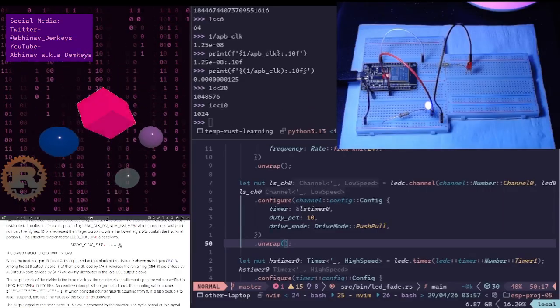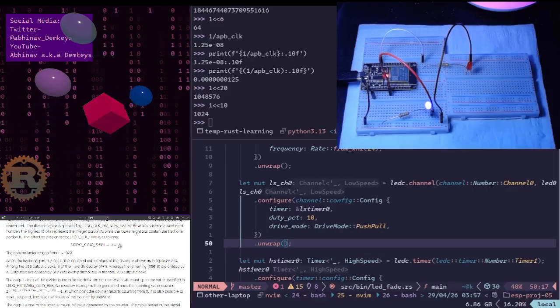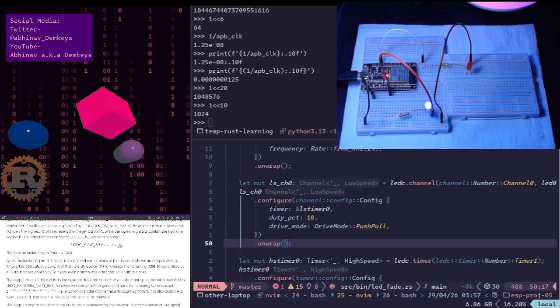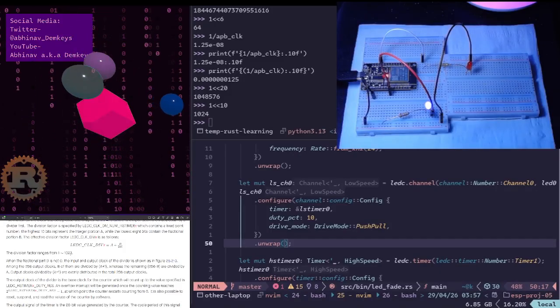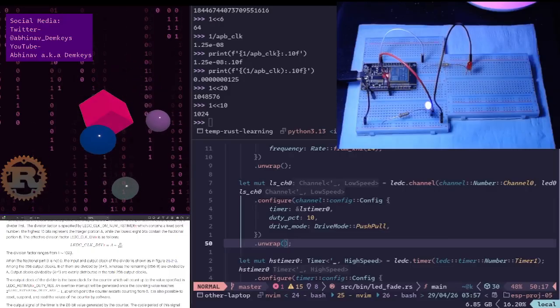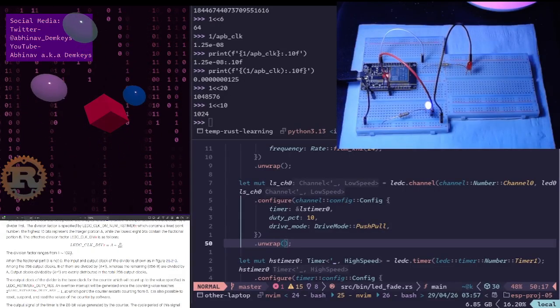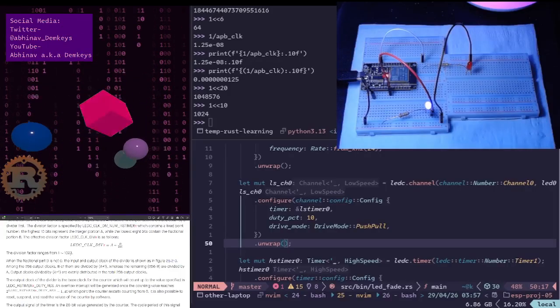I was about to say because it counts from 0, but that's not what's happening here. Either way, 1023. So we only get 10 bits out of that 18-bit register, meaning our divisor can only be anything within this value.